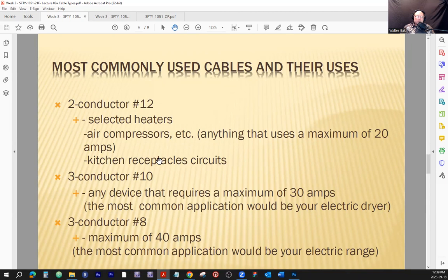Plus, instead of having one duplex receptacle, which means the two receptacles act as one, we are going to separate them by removing the tabs on the side so that each screw terminal is powering an individual receptacle. To one of them, you're going to run the black wire, which is one of the hots, and it goes to a separate circuit breaker in the panel. To the other one, you can apply the red wire, and that can go to another separate breaker, and they can both be 20 amps. So, they can service a lot of amps.